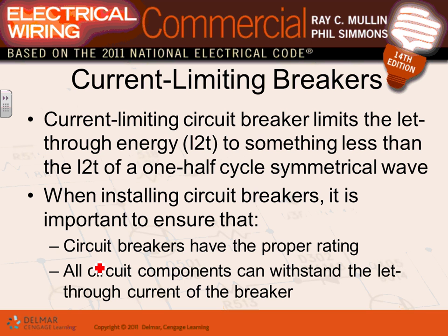Current limiting. Guys, there's a concept called I squared T. You're going to hear this one all the time, I squared T. What fuses typically do is, when they interrupt within half a cycle, they limit the energy that the equipment will be encountering. Who cares? After a short circuit condition, your equipment will not burn. Is that a good idea? Current limiting breakers or fuses will limit the I squared T, which is the energy that the fault will generate, by interrupting the fault within half a cycle, and that in turn, guys, will protect your equipment.